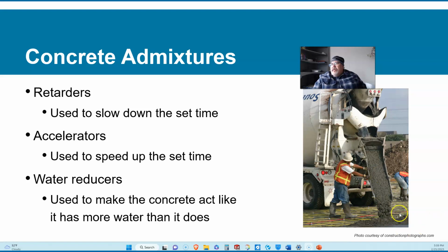Well, that's also dependent on temperature. So what if we wanted to cure closer to 12 hours and farther away from 4? We'd use retarders. Or maybe we're working in colder temperatures and we can't wait 12 hours for the mixture to solidify. So we use accelerators to speed up the set time.